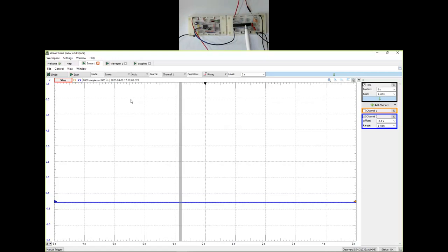The counter is to the right here, where the outputs of the 4-bit counter control how the LEDs come on and off. So I'm essentially connecting the output of the timer chip, which is pin 3, the clean pulse, to the input of this inverter.